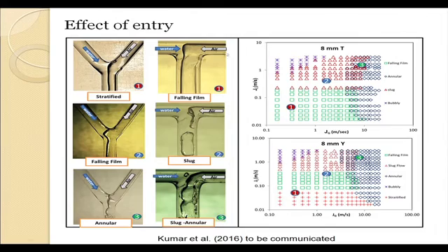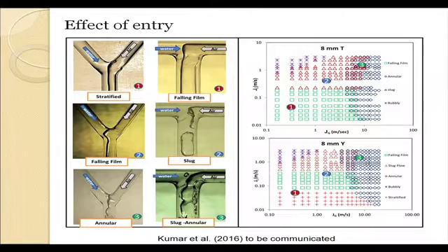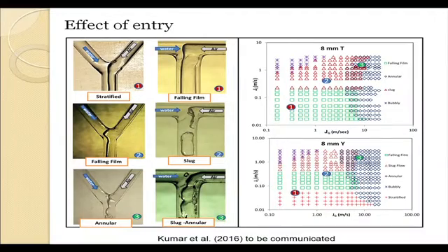So that is the reason why these two flow patterns have been differentiated and marked by different symbols in the flow pattern map here. Well, again I have digressed from what we were trying to discuss, but I thought it's important to clarify this point, because so long we have just been dealing with bubbly, slug, churn and annular. Suddenly here I have introduced the falling film, and it might confuse the students that if falling film is annular, then why use a different nomenclature.